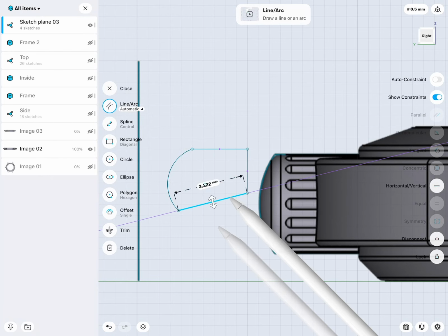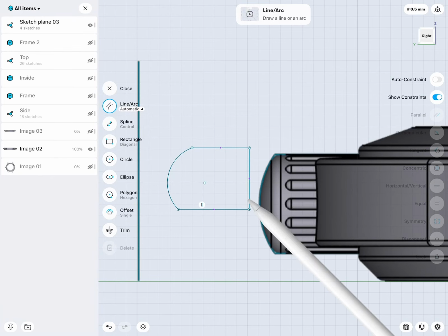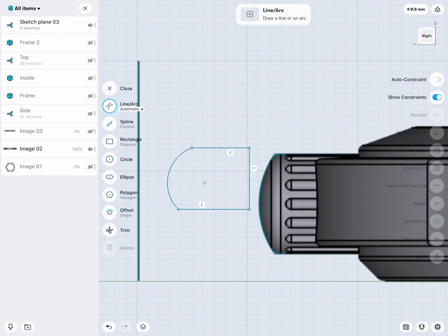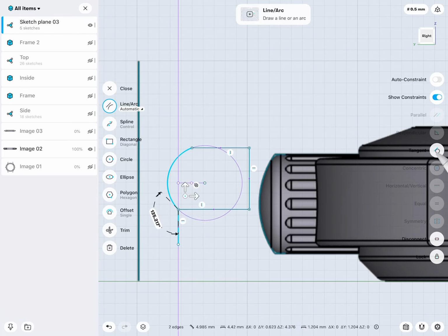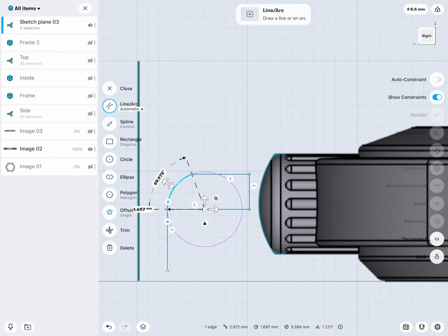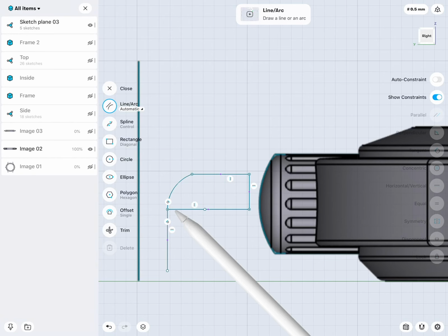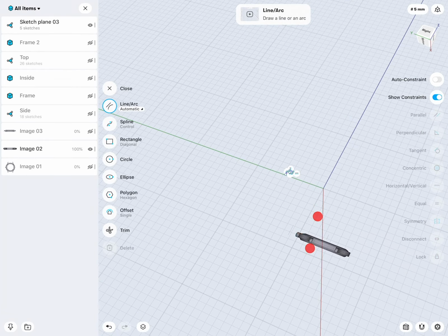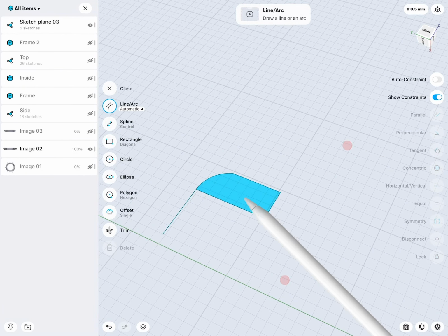Connect this, then this will be horizontal, vertical, horizontal, and here I will draw a line down, make this line vertical, this line and that arc be tangent, and now you see that this arc terminates perfectly perpendicular to this line, so when we revolve the filling to the other side, it is exactly where it needs to be.